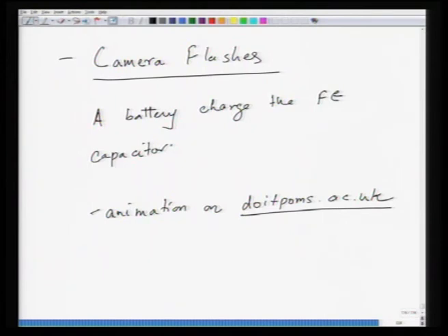And so, this is basically the end of this part of this module on ferroelectric materials. Essentially, ferroelectric materials, in summary, are non-centrosymmetric polar materials, where the direction of polarization can be reversed by reversing the direction of the field. They undergo a transition which is called the Curie transition. Above this Curie temperature they are paraelectric, and below this Curie temperature they are in the ferroelectric state, and this is basically a phase transition. It can be a first order or second order transition depending upon the material, but it characterizes a change in the phase or structure of the material.